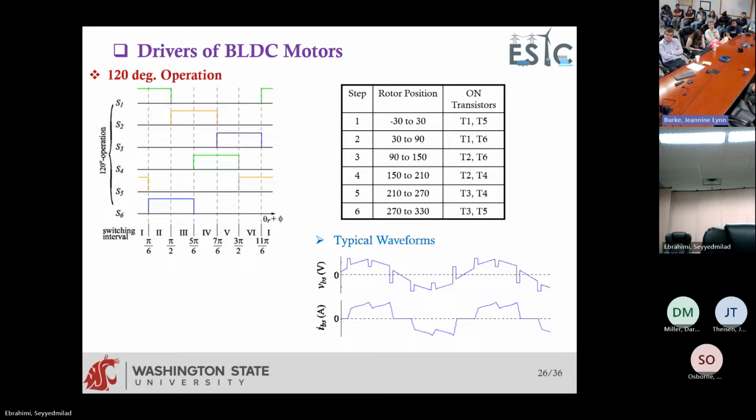So these cause these notches in the voltage waveform. For example, here, this is where two other phases are trying to switch. That causes this notch. So these imperfections in the waveform are harmonics, and these imperfections cause harmonics of the current.